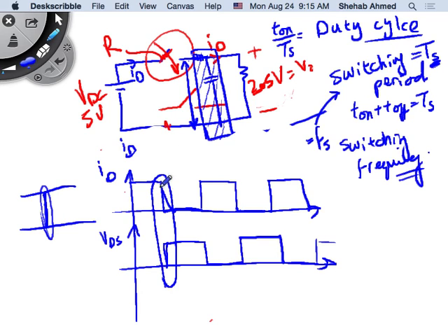But if they see each other, no, not really, I mean, this was a bad joke. But really what's happening is that current and voltage will see each other, because current will fall slowly and voltage will start rising. So there will be a period where they're overlapping. So there will be voltage across the device, and there will be current through the device as well, which means that there is power loss, right? So if I am switching fast, then I'm increasing my switching losses.